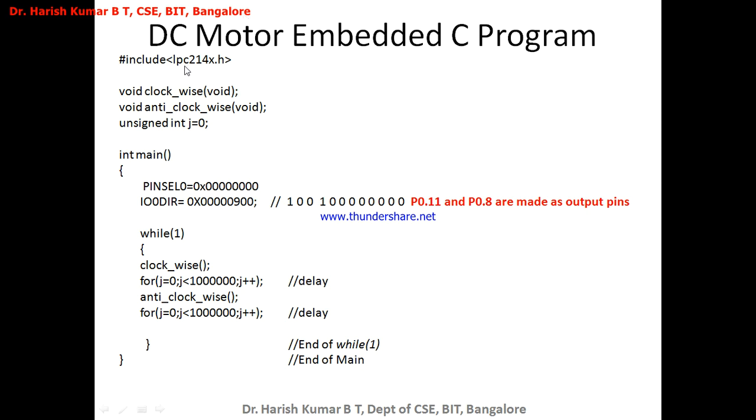Now you have to include the header file LPC214x.h, because this header file applies for all the LPC214 series: LPC2148, LPC2142, LPC2145, etc. Instead of this 4 I can also put X, because it also holds good for the LPC21 series: LPC2138, LPC2132, LPC2135, all these.